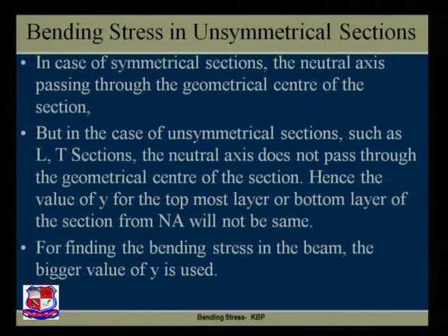But in the case of the unsymmetrical sections such as the L, T and unsymmetrical I sections etc., the neutral axis doesn't pass through the geometrical center of the section. Hence, the first step is to find out the distance y from the topmost layer or the bottommost layer of the section to the neutral axis, and those distances are also not the same. Hence, for finding out the maximum bending stress in the beam, the bigger value of y is to be used.